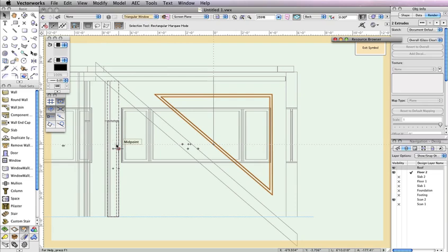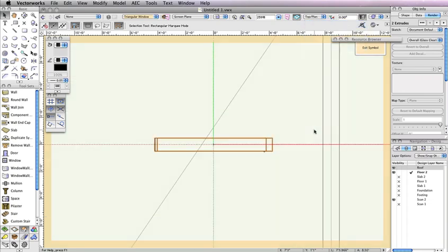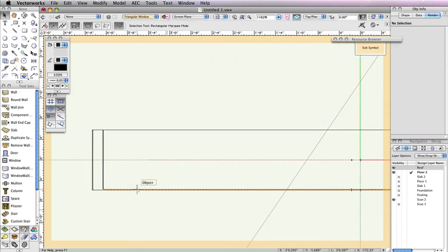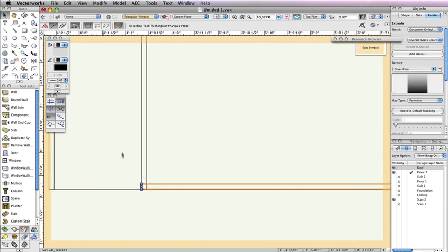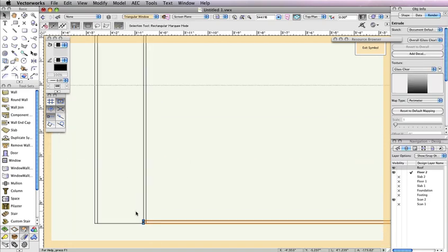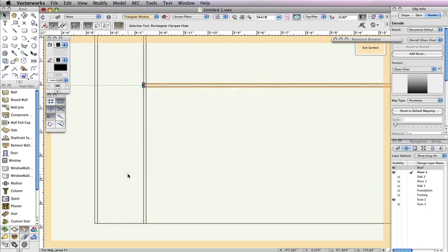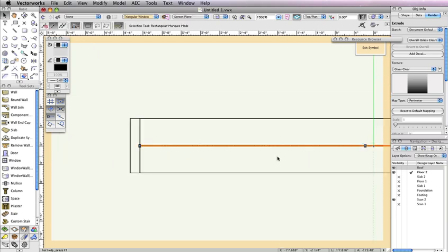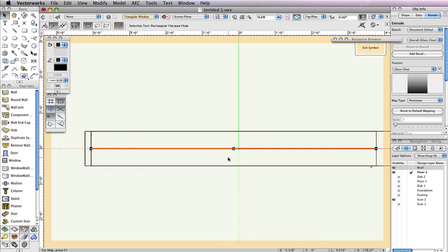Although the window looks correct from this view, when you switch to a top plan view from the view bar, you'll see the glass pane is not centered in the frame. To center it, zoom in close enough so that you can see and select the thin extrude at the bottom. Then click and drag this extrude by its left end point. Snap it to the midpoint of the edge it shares with the frame. You've set the glass pane position in 3D.